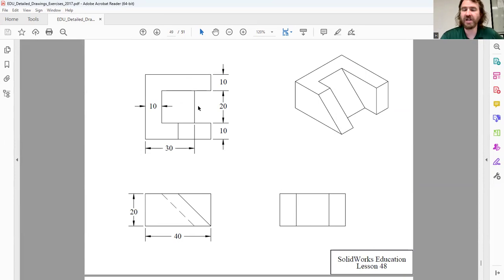That's a possibility. The issue is if it's all one body of 3D material, it's going to be hard to get these two chamfers done with the chamfer tool doing one body of material, one extrusion, or two extrusions that are connected like this view would suggest.